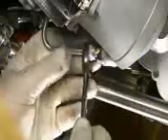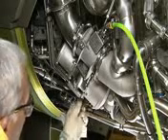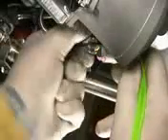Remove the control line from the HSV and attach one hose from the high stage test assembly to the control line, and the other to the HSV.